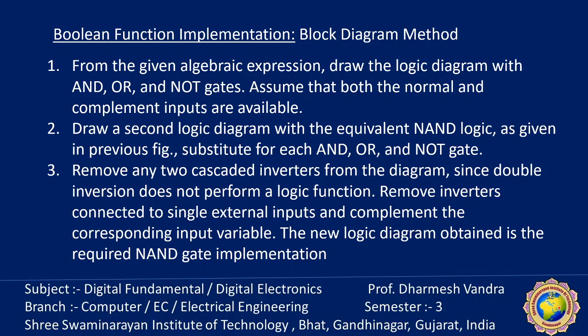Then connect a single external input and complement the corresponding input variable. The new logic diagram obtained is the required NAND gate implementation. Let's take one simple example.